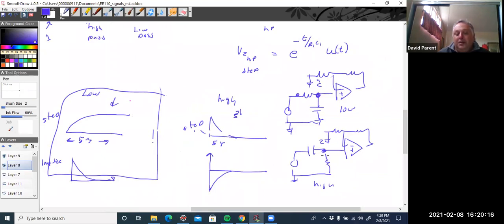But when you look at one of these circuits, when is it DC? Oh, it's open. When is the frequency really high? Well, then that makes it short. And just by that, and actually it wasn't even voltage division, it was the current is 0, either it's a wire or it's open, or there's finite current and no voltage drop, or 0 current and no voltage drop, right?